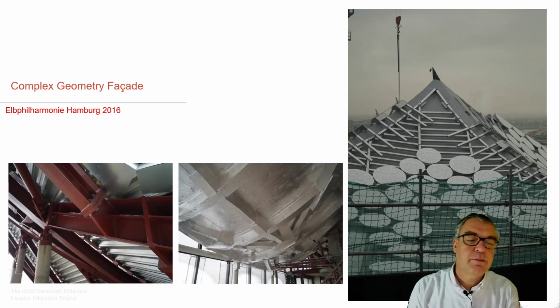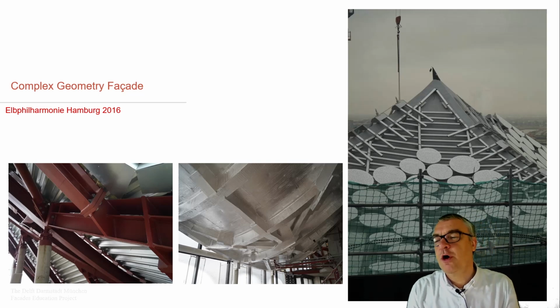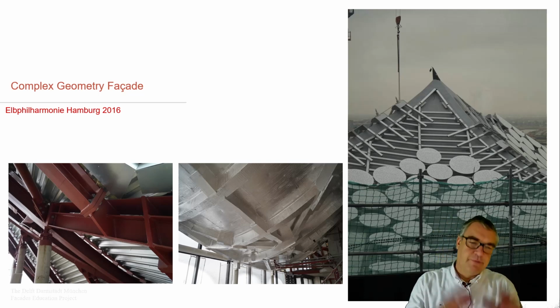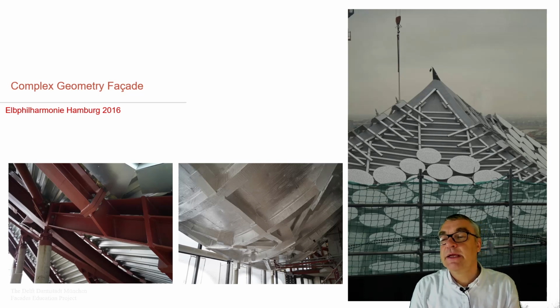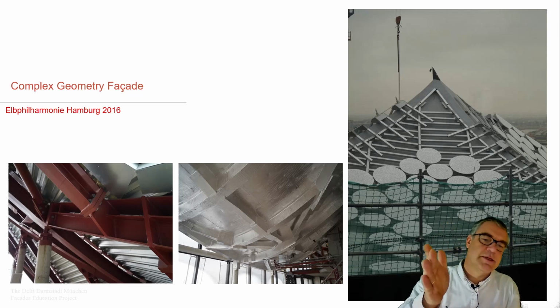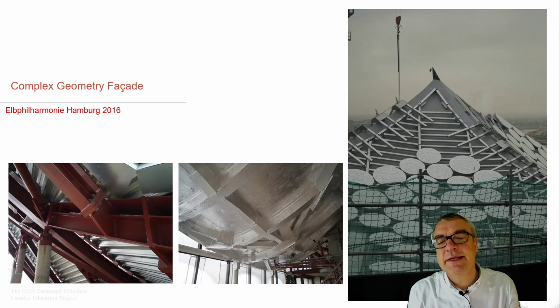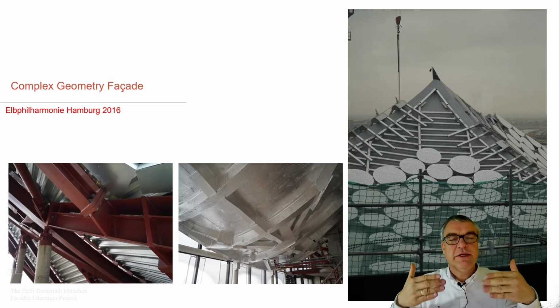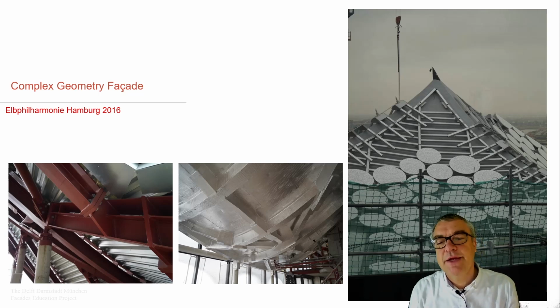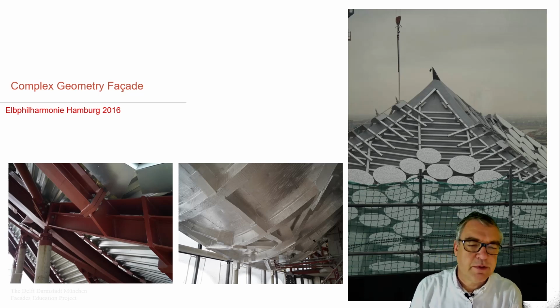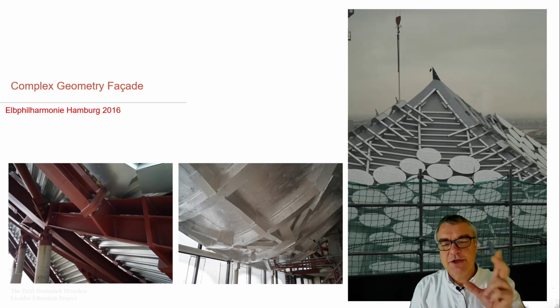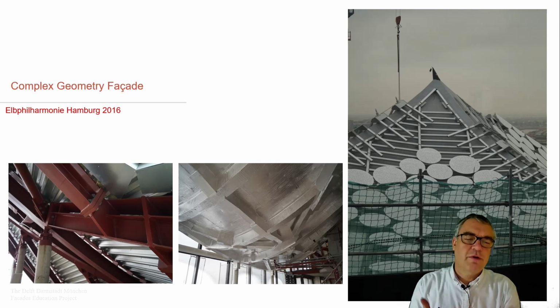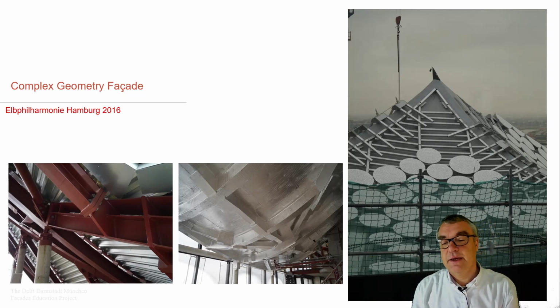And when we go inside the building, we see it's a super free-form geometry, which, in the functional zone, needs to get insulated, and then the airtightness at the inside needs to be entirely sealed to make sure that no humidity gets into the system. You can imagine that all this aluminium foil being brought in position is quite intensive craftsman work, and leakages appear where the craftsman doesn't work perfectly, or where you're not able to get your fingers in to get the geometry done. That can be very intensive work.